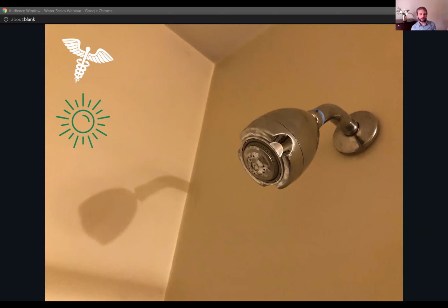So typically, you're going to see most of the time 2.5 is sort of your higher end, then 2.2 gallons per minute, then 2 starts to kick in for the green programs, 1.75, 1.5, and then ideally we'd like to see shower heads down to 1.25 gallons per minute.